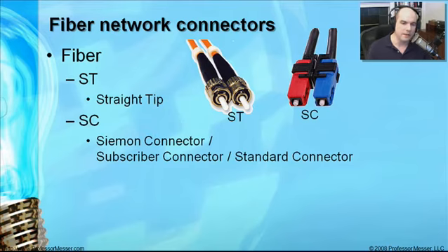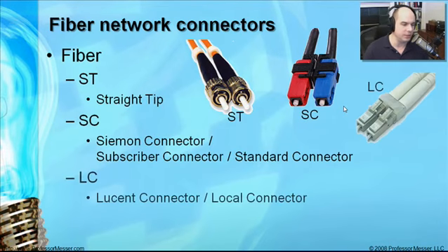A more common, but still a little bit older style technology is one called SC. And again, we're not really calling this the Siemon connector, the subscriber connector, the standard connector. It tends to have many different names. It is simply SC, Sierra Charlie. So if you're on the telephone and you're ordering equipment or you're saying what type you have, ST and SC, you can mix those up very easily. So make sure you're very clear that you're either asking for an ST connection or an SC connection, because as you can see from these pictures, these are very different connections whenever you try to plug them into the devices that you're using.